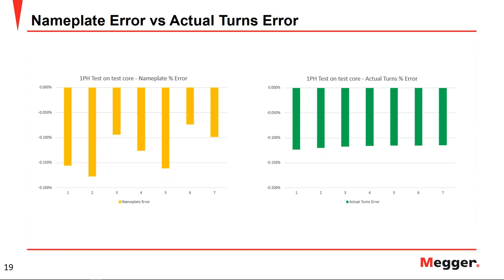So you have the voltage ratings for those positions in the nameplate of the transformer. Neither the software nor the instrument itself is doing any compensation. You're actually measuring the ratio for all the different positions. And then with each result, you compare to the corresponding ratio that you calculate from the nameplate.